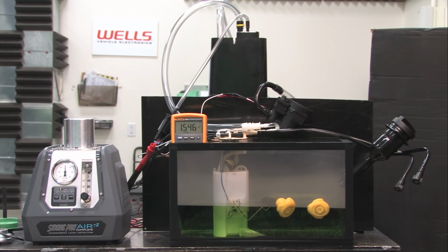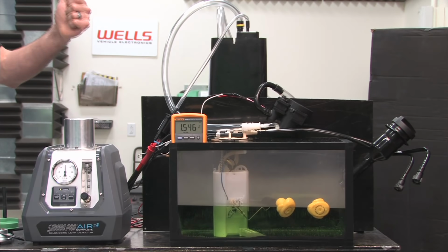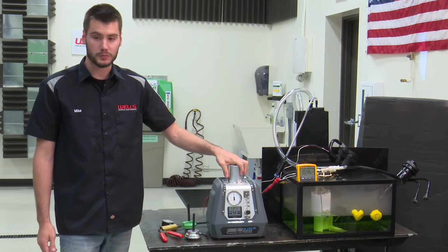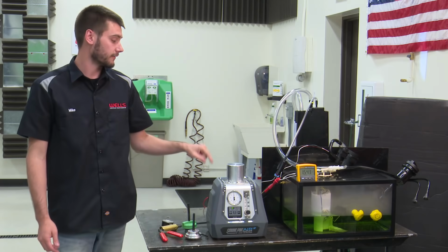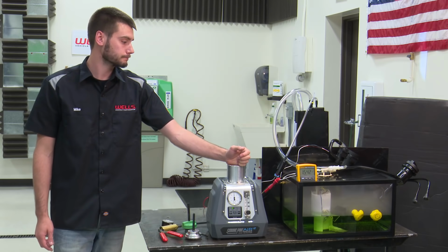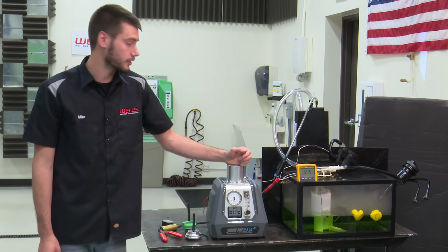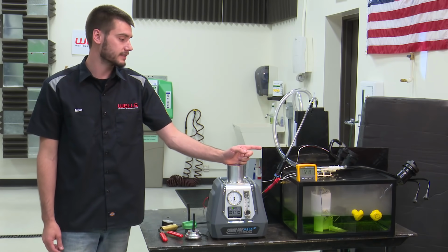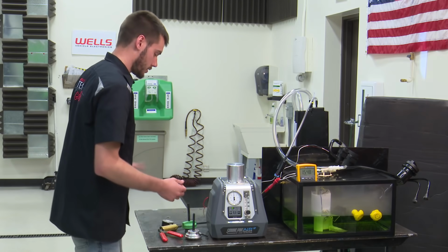Now, this is, again, a GM fuel tank pressure sensor on here. What's unique about GMs is if we pump pressure into this system, if we use this smoke machine and pump pressure into there, we're going to see that voltage go down. If we suck vacuum on the system, we're going to see that voltage go up, which is kind of backwards of thinking, and it's actually backwards of a lot of other vehicle manufacturers. So if you're checking fuel tank pressure on a GM, make sure you realize that pressure will make the voltage go down, vacuum will make the voltage go up. So let's go ahead and do that.